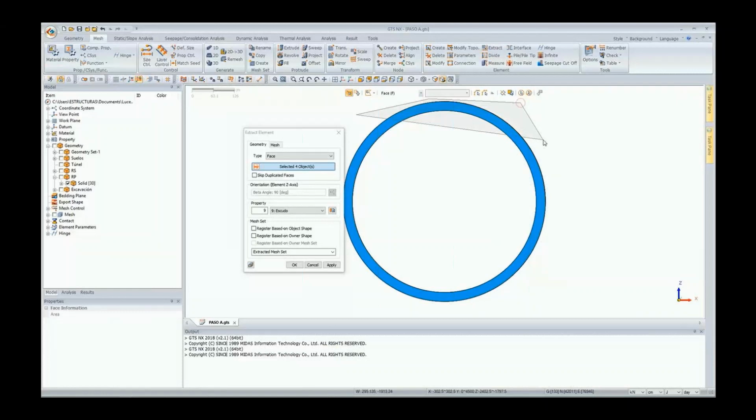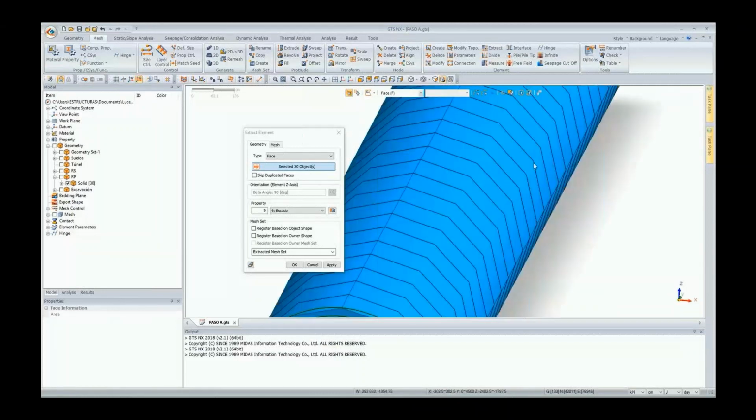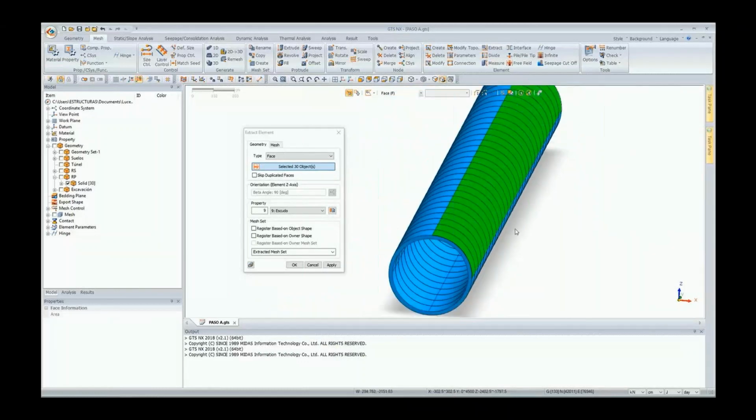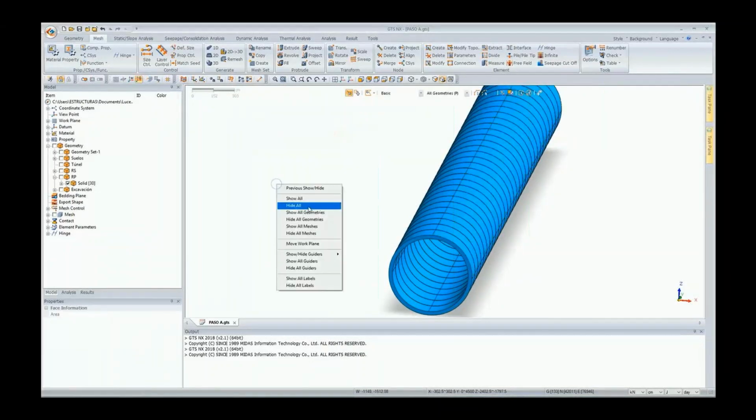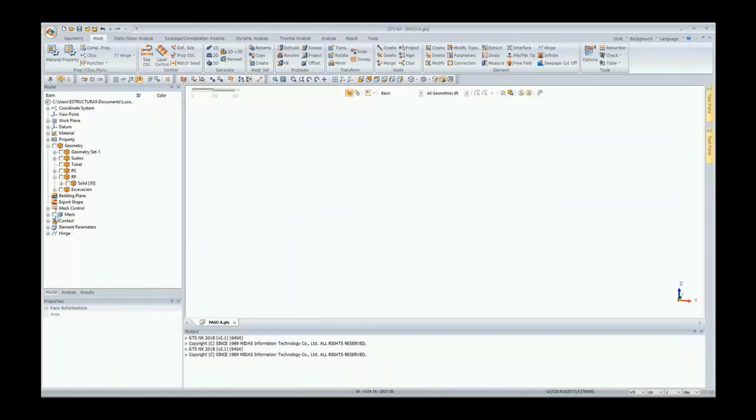With this one, I can generate a series of polygons and then close it off to make an irregular area. And whatever is selected under these will be captured. So we see here that if I carefully make a volume or an area for these outer rings, it captures everything under that direction. So we would have to repeat that step for all the other outer sections, and then just assign the shield material property to the 2D shell. But again, to save a little time, we have already done that step for the whole outer face. So I can just show you here in the worktree wherever this corresponds to.